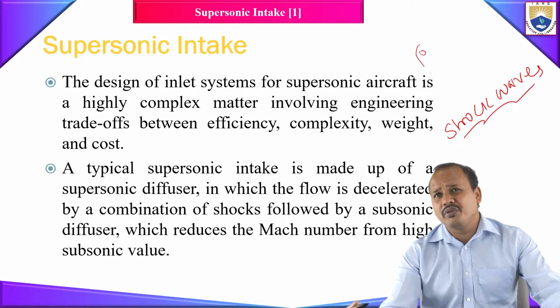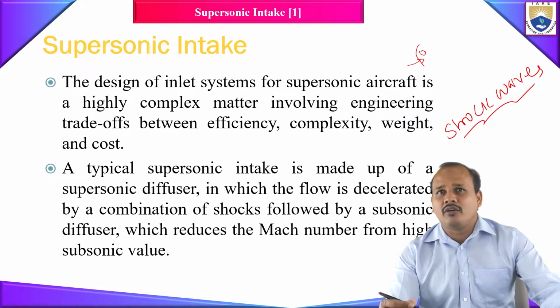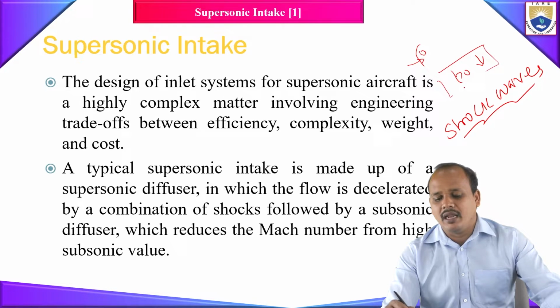Now, you could ask, why do we bother even if the shock wave is forming? The process across a shock wave is a non-isentropic process, the entropy increases rapidly. Entropy increasing rapidly means the loss across the shock is very, very high. As you know, one of the basic requirements of any intake is that it has to decelerate the incoming flow to the required Mach number with the least amount of total pressure loss. The loss in P naught should be very, very small.